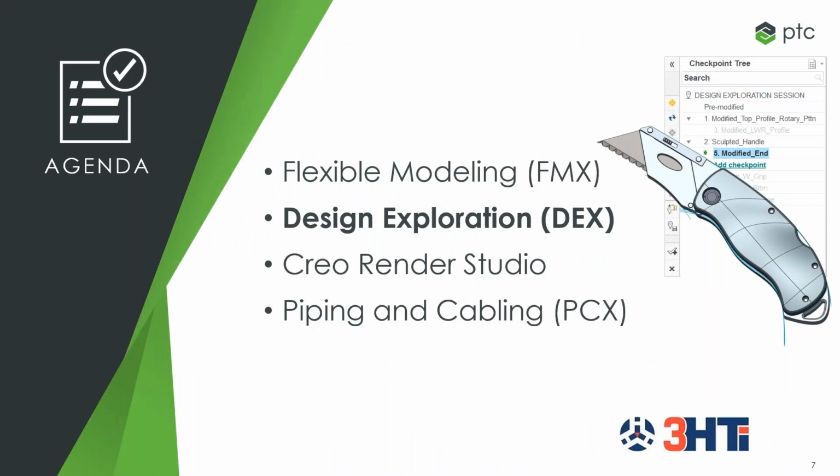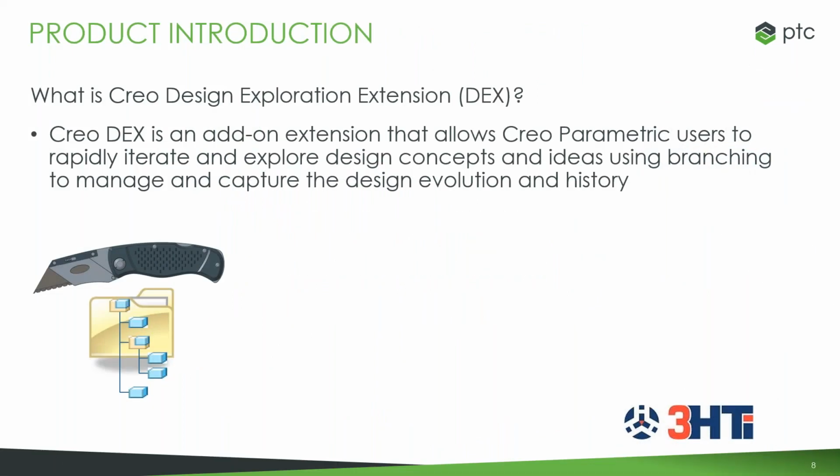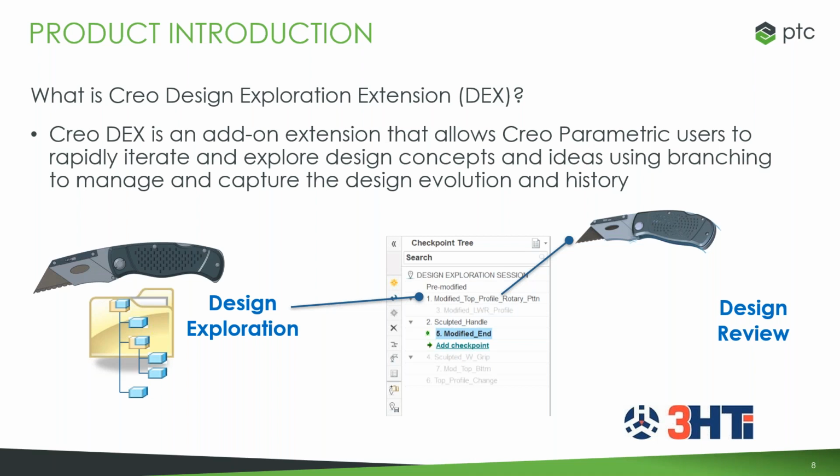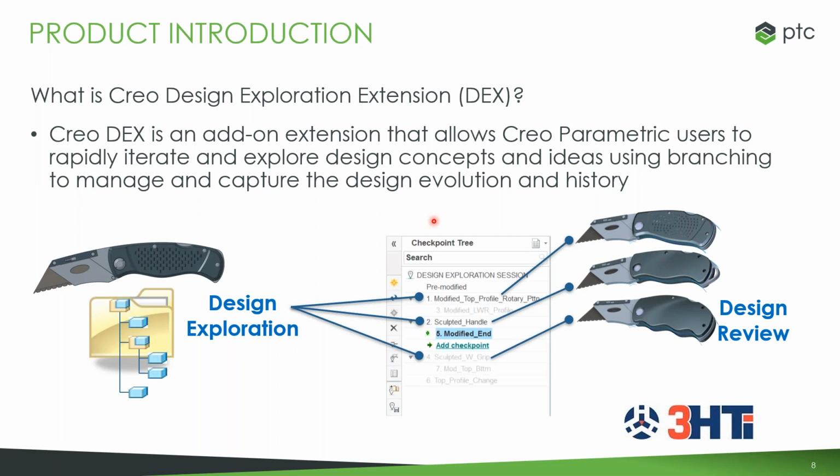All right. So the next one I'll touch on here, design exploration. Design exploration is an extension that is useful at the front end of the design process when we're just working through ideas. It allows us to create checkpoints as we're trying out different ideas. So maybe I want to see what this looks like. All right, I have that. Make a checkpoint, and now I want to go look at something else. Whatever I think of, I can just make and add as additional checkpoints, and then very easily switch back and forth between them to compare and contrast.